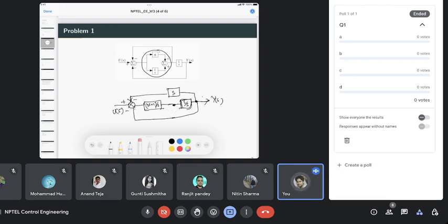So it will be S, right? Now again you have this signal here. This signal and this signal are both coming to this one summing point, so they can also be added together, and with this minus sign there, I can have a one block here instead of that. Because initially it was S in the above and plus 1, so I can write it like that. Is it clear? So then you just apply the feedback formula directly.